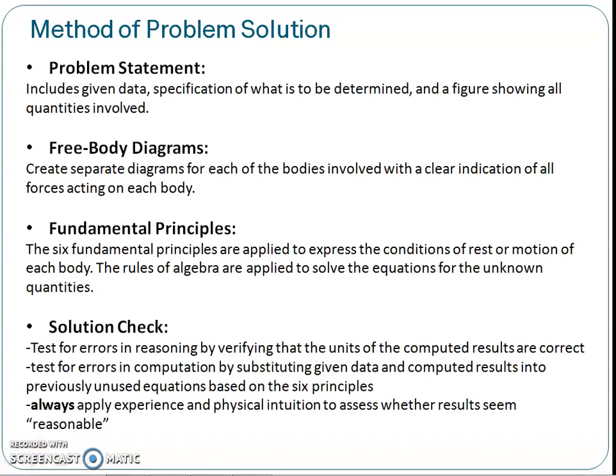In solving problems involving dynamics, first we have to understand the problem statement. We need to include the given data, the specification of what is to be determined, and figure out what quantities are involved. Next is the free body diagram, FBD. We create a diagram of the bodies which involves all the forces acting on each body.